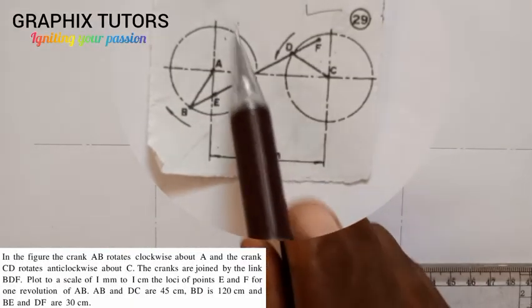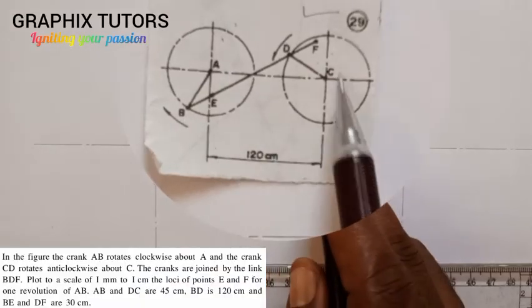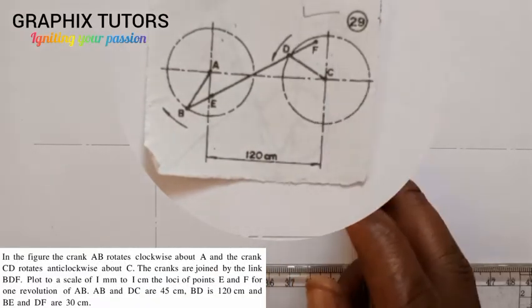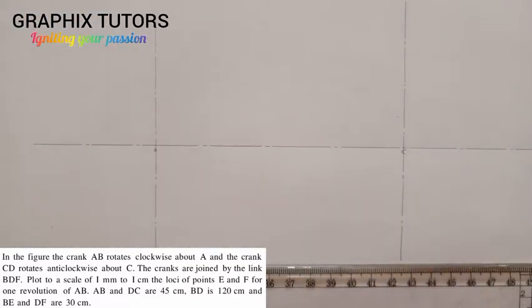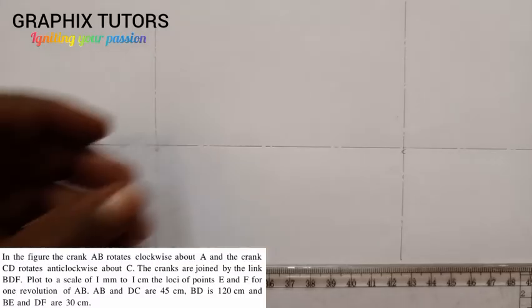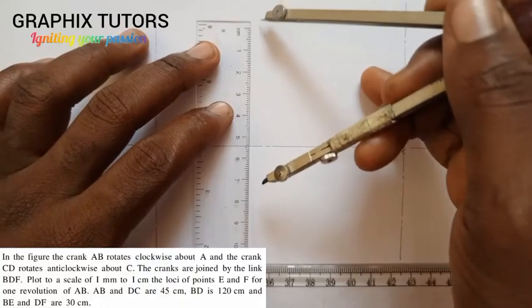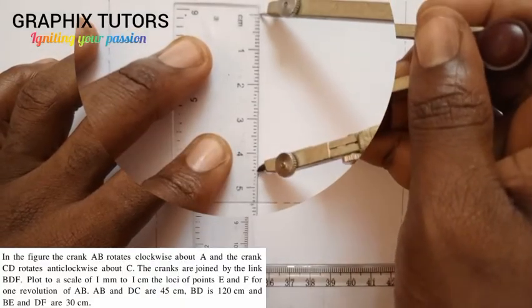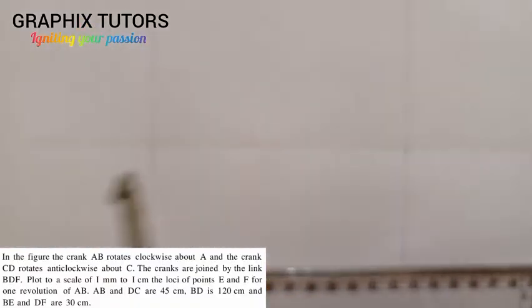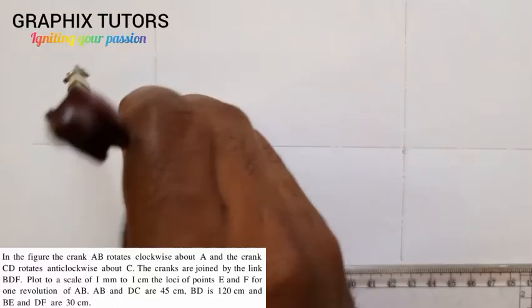Now the next thing is to draw the crank, and we're told that AB is equal to CD, which is 45, right? So we'll draw our 45. I'm going to take my compass and draw. With the help of my meter rule, I'll place it at 0. Now I'll take it to 45 here and put it at point A, right?